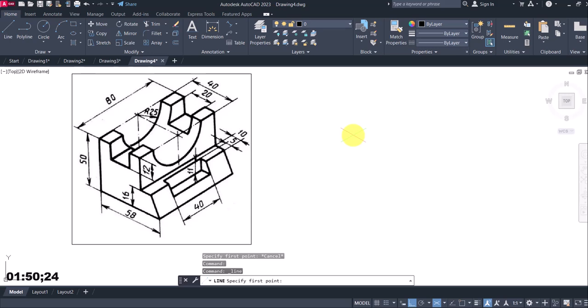So I'm going to change my ISO draft. That's because of the choice of our ISO draft here. When you look at this icon, you can see that our ISO draft comes with three different icons, similar to our cursor. For instance, your isoplane top has this X sign. If I switch to isoplane left, you can see the sign I have on my cursor. If I switch to isoplane right, you can see the sign I have on my cursor. So this sign is actually telling me the possible movement I can achieve with each isoplane.